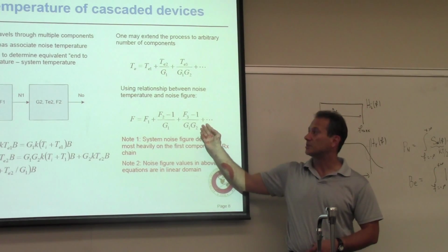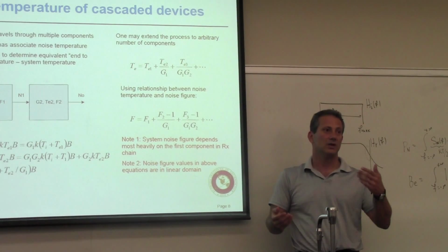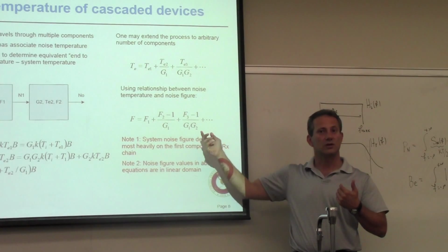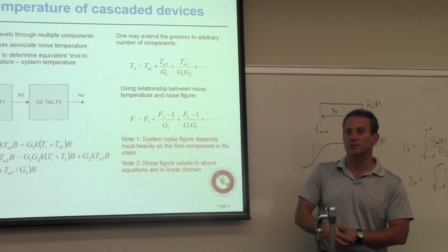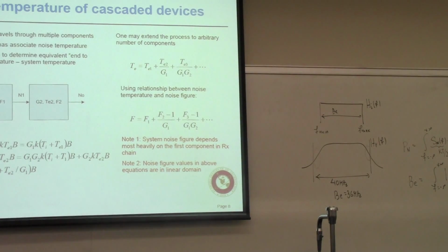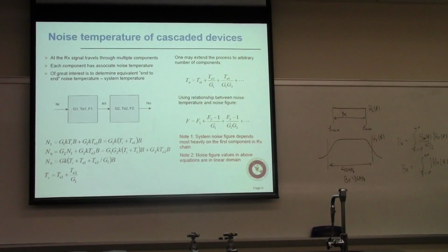Right? All these numbers, if you're not given linear noise figures, they would say the noise figure is 2 dB, 5 dB, 10 dB. To do these calculations, you have to bring it into the linear domain. Okay, and I'll do calculations. So if these were attenuations, then that would destroy your noise figure if you cascade them?